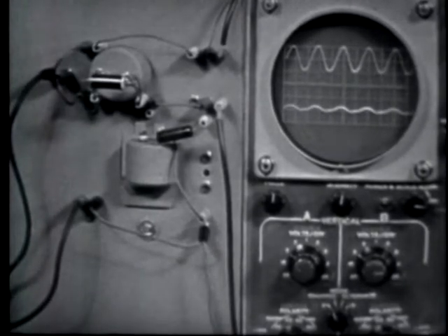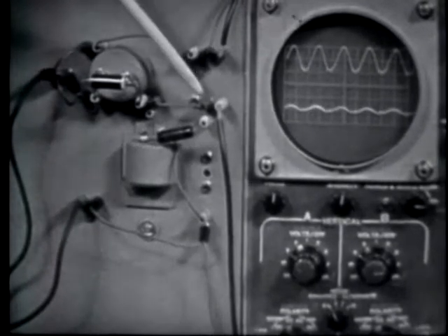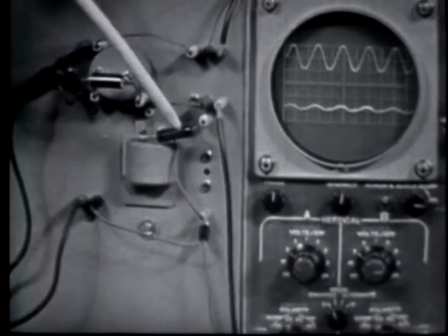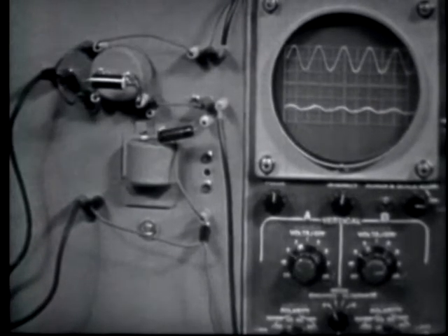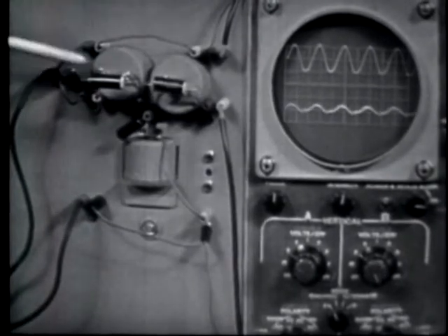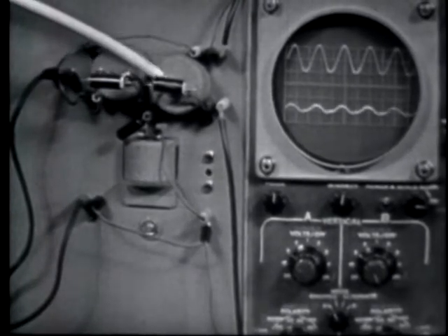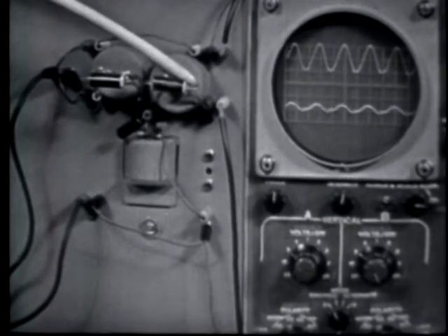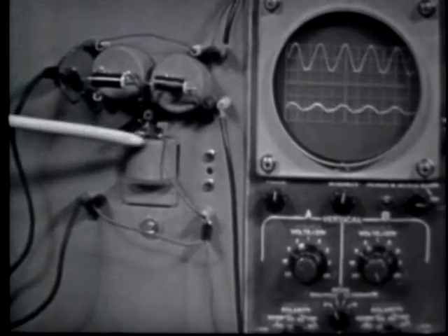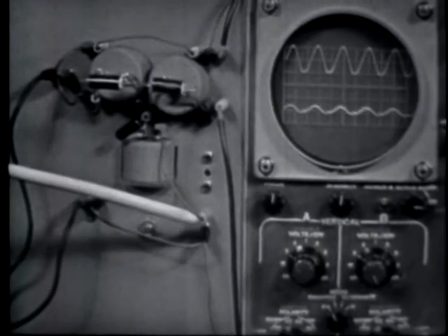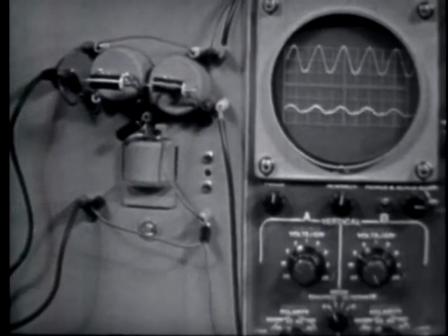So let's make a T section from this basic L section and see if we can improve the frequency response. Now, to make the T section, we'll need another parallel tank in the output leg of the series position, and we'll need to move our series tank over to the junction between the 2 parallel tanks. Now let's do this. Okay, parallel tank here in the input series leg of the filter and a parallel tank in the output series leg of the filter. And our series tank now is connected from the junction of these 2 tanks down through the capacitor, the inductor in series, and down to ground. So we have a T section band reject filter.